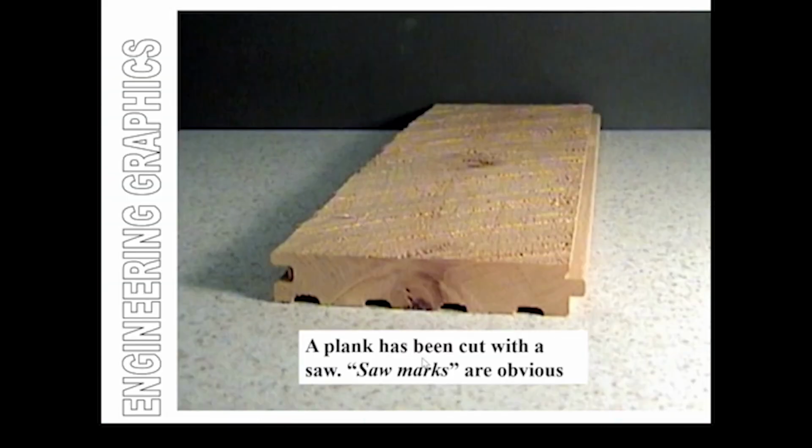But when it's not possible, we generally go through a system that's called sectioning. And sectioning really means that we pretend we are cutting through an object to reveal the inside details.